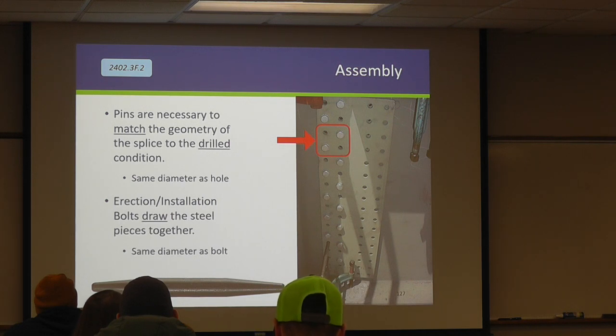And even though we think of steel as being very rigid, when you get to some of these heights, like 7 feet tall, 15 feet tall, and this is only a half-inch thick plate, it's really flexible. Right? And so I'll show you a picture here in a little bit. I've seen some of these splices where they have up to 600 bolts in them, that if they work these connections wrong, you can fill up a quarter of the hole with these half moons.